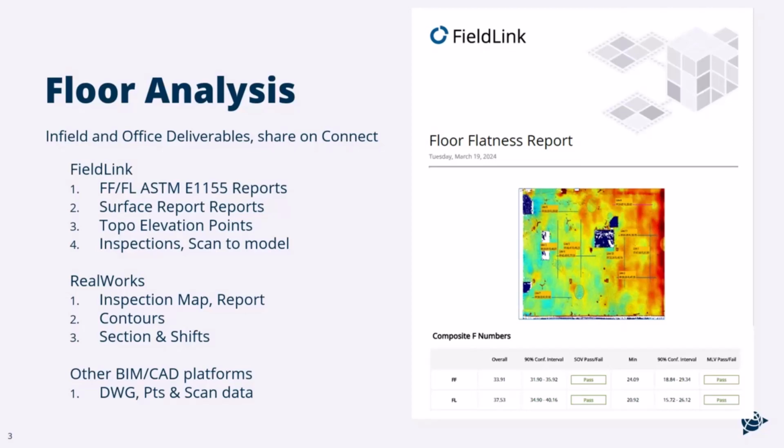You can actually use the scan data to see where you may have issues if you run lines just based on the elevation view like you see here, with red being high and then green being within that tolerance of elevation that's probably there. If you go across those, you may run into some issues. But you can also see where those lines were drawn, and if they were too close to a sleeve or an opening, it documents it.